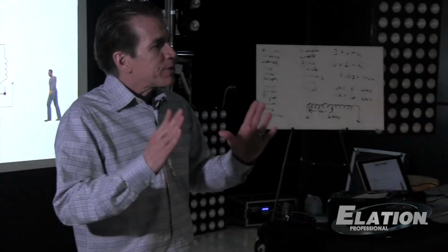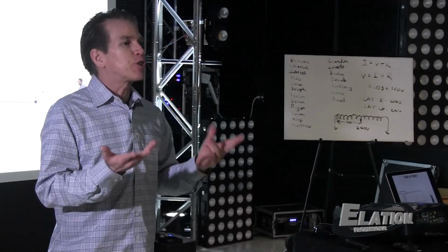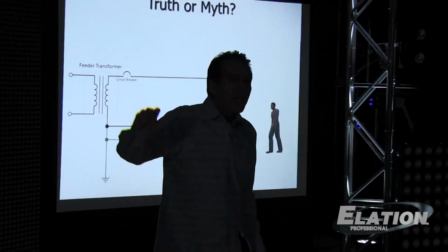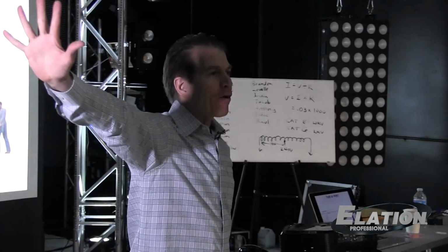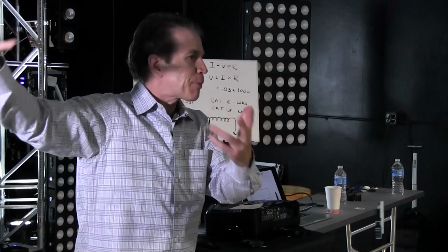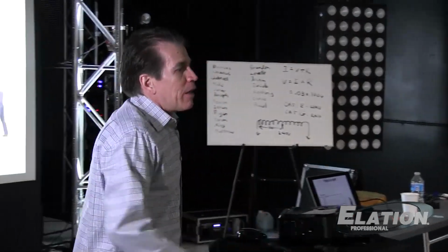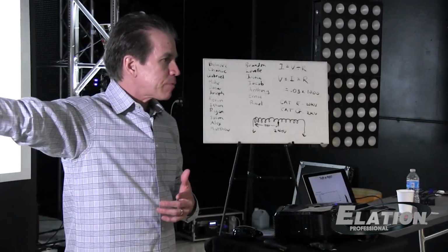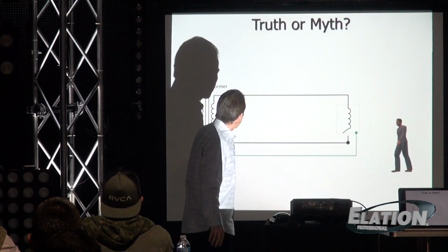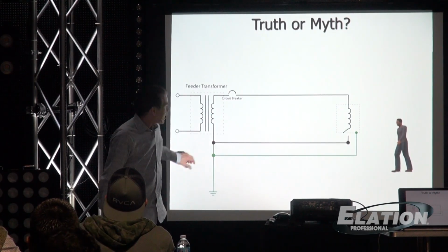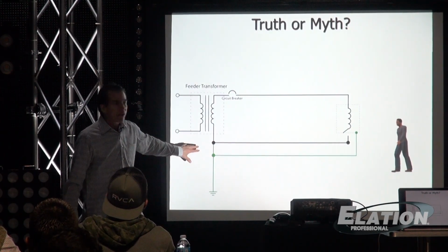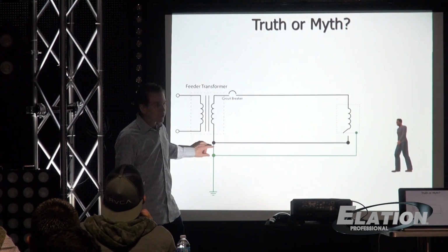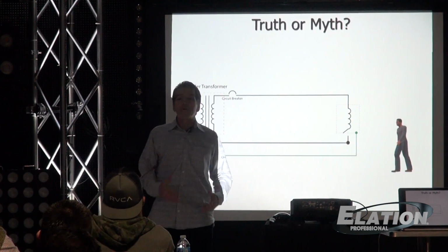Now they bring these onto the set when they're doing a location shoot, and now they're not using the portable power generator on the honey wagon. They've got their own base camp with portable power generators, big power plants. They're feeding power to the honey wagons from their plants. Well, if they don't break the connection at the honey wagon and they go ahead and run power up to it, it's as if there's a connection here and there's a connection there. So now they have current flowing through the green grounding conductor.